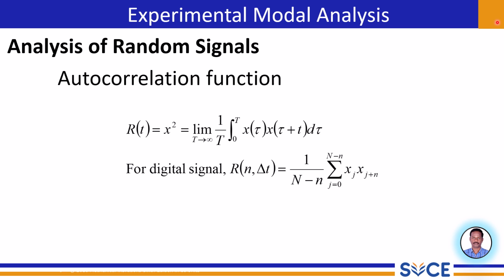In experimental modal analysis, we often focus on frequency domain techniques like FFT. The autocorrelation function can be a valuable tool for analyzing the time domain characteristics also. It can help us identify periodic components that may be related to structural resonances or external forcing functions. For instance, if you are using random excitation to excite a structure, the autocorrelation of the input force should ideally be a sharp spike at zero time lag. Deviation from this ideal can tell us about characteristics of our excitation source.